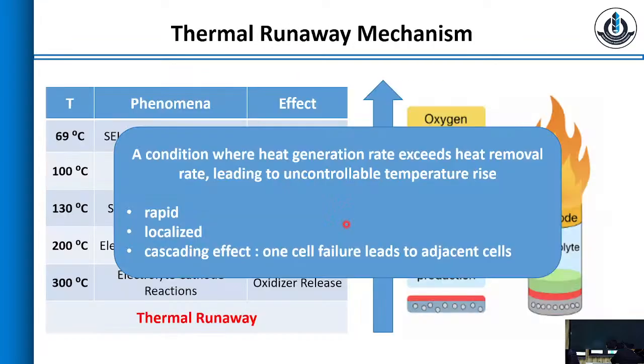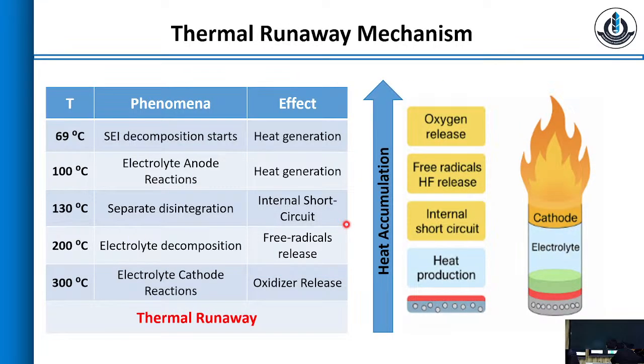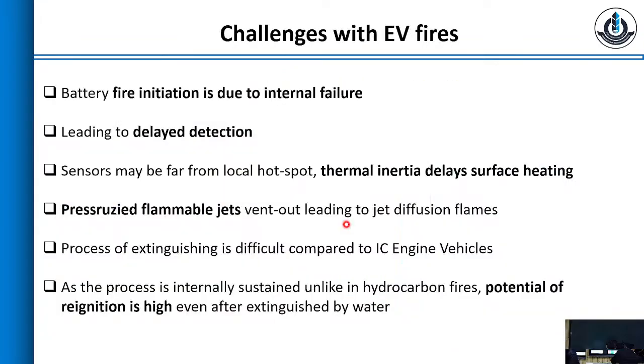But what happens is, once the battery has lost its structural integrity, there are still internal reactions that will be going on. Right, your electrolyte decomposition, these electrolyte cathode reactions might be still going on internally, even though we have reduced the external temperature. Okay, so once you do that, after a certain time, probably 3 hours, 4 hours, this will again start to burn. Okay, so that is the challenge. So the problem of reignition is very high in EV fires.